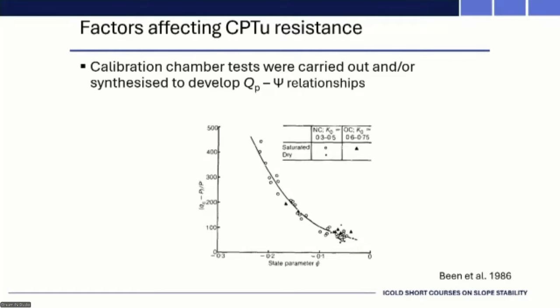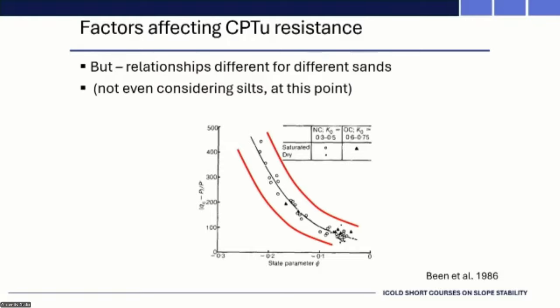So, valuable as it was, we were very reluctant to be extrapolating that line into the positive state parameter territory. And you can see, particularly between 0 and minus 0.1, there seems to be more and more scatter. So any extrapolation is going to become more and more dodgy. And you could envisage putting bounds on that, which then straight away negate the value, I think. So it's very valuable, and it's good to be able to interrogate some of this data, but clearly